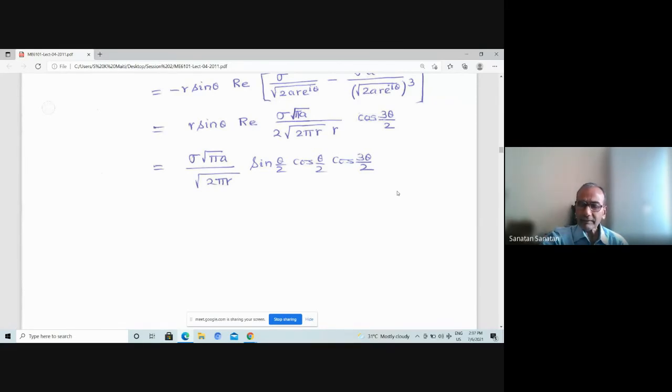And in the case of 2 dimensions, the problem can be tackled by the Airy stress function approach, which helps us to really simplify the problem in terms of a single function rather than 3 functions of stresses or 2 functions of displacements. And that stress function in 2 dimensions can be written in general in the form of 2 analytic functions. Analytic functions are easily constructible and they can be exponential functions involving exponents of z. That's why it is easily constructible, and therefore you try to get the right combinations of these exponential expressions so that it satisfies the boundary conditions of stresses. That will solve the problem.